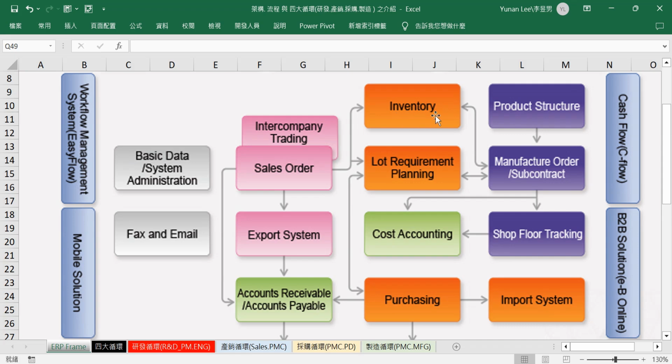Once we have the finished product and the part numbers for semi-finished products and raw materials, the next step is to build the BOM structure layer by layer. This will use the product structure module for the BOM creation function to include all materials or semi-finished products, and assign them one by one to the part numbers of semi-finished and finished products. This creates a complete BOM.